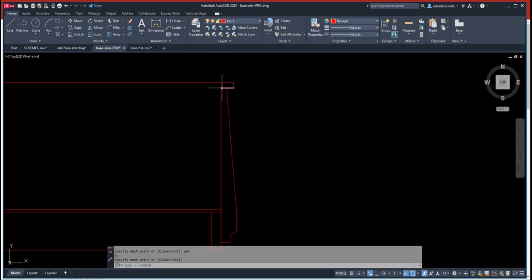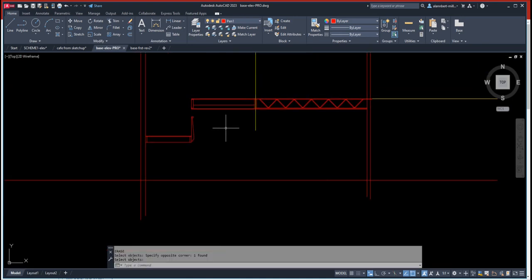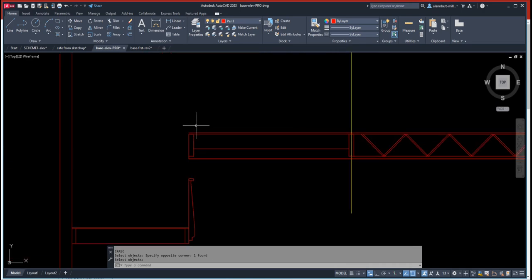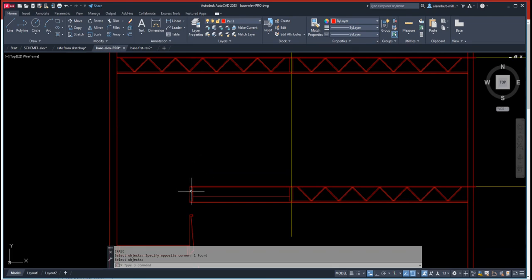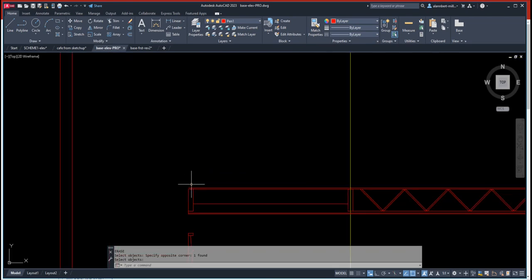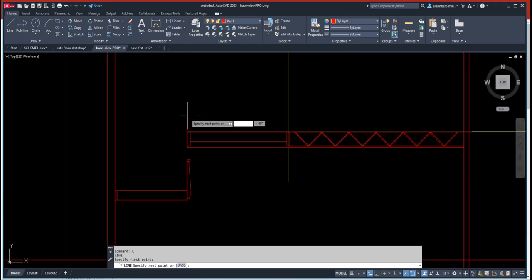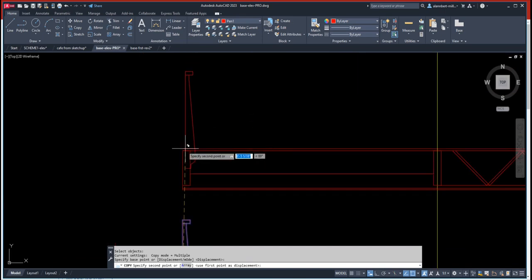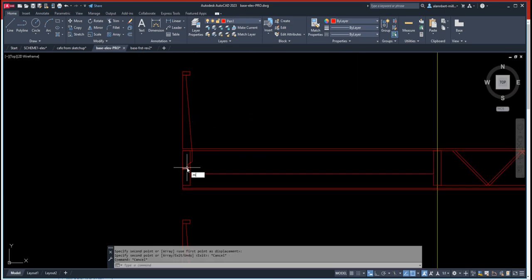Okay, and that's my railing. Okay, so I probably would put a glass there, but anyway, that's what the case is. Now there's a handrail or guardrail here, so we're gonna put another 40 inches up here. We're gonna do an offset. Oh, just do a line from here, and we can just copy this. Let's just copy, CP, and we're gonna copy this and that one too. And it goes to that corner, and we're gonna do that to this corner here, and then we're going to just mirror that thing